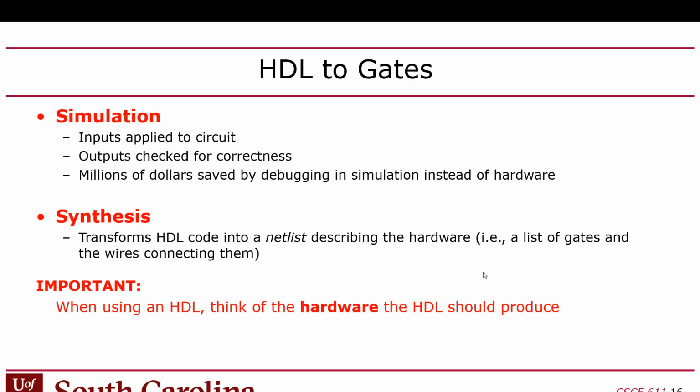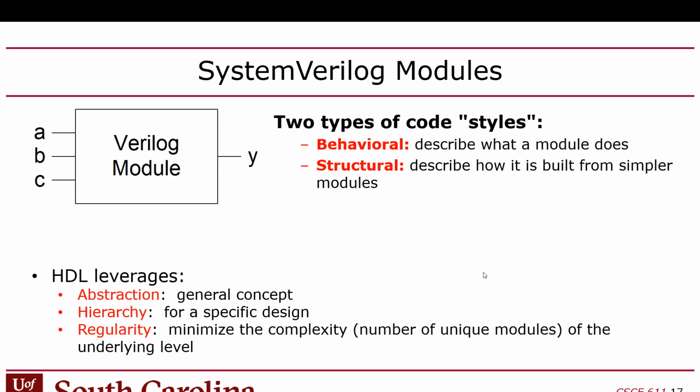But we wanted to teach it just so when you go in industry, you'll have experienced it. If you don't want to use this commercial tool, there are free ones available. The most commonly used one's called Verilator, which is pretty cool, actually. There's one called Icarus Verilog and Verilator. Both of them basically convert your code into an executable that you can run natively in Linux, which is kind of neat. And also you can more easily interact with it through C code, your software. But anyway, we're not doing that. Eventually, I'll probably switch to that. But for now, we're using this ModelSim.